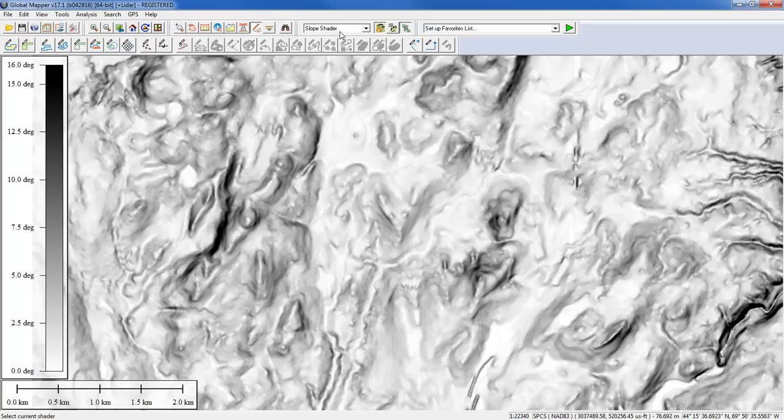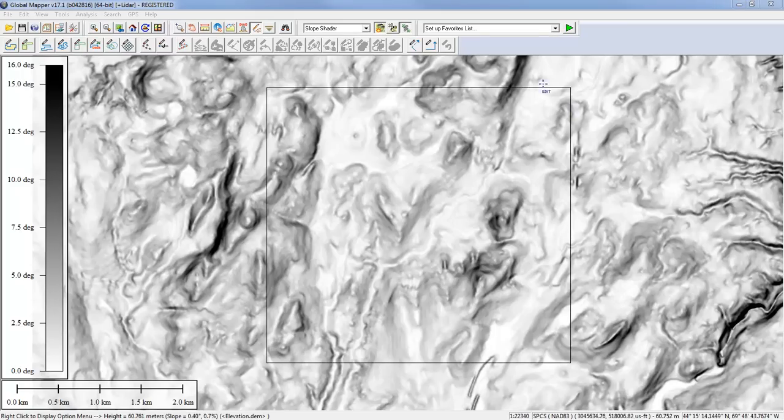The other way that I'm going to visualize slopes is through the assignment of a quiver plot, or an arrow if you like, to points on my screen. Now the first thing I'm going to do to initiate this process is to define the extent of the area that I'm going to analyze. I've already created a polygon, a rectangle, within which I'm going to analyze. Now my intention here is to create a point at a fairly regular interval within the extent of this rectangle.